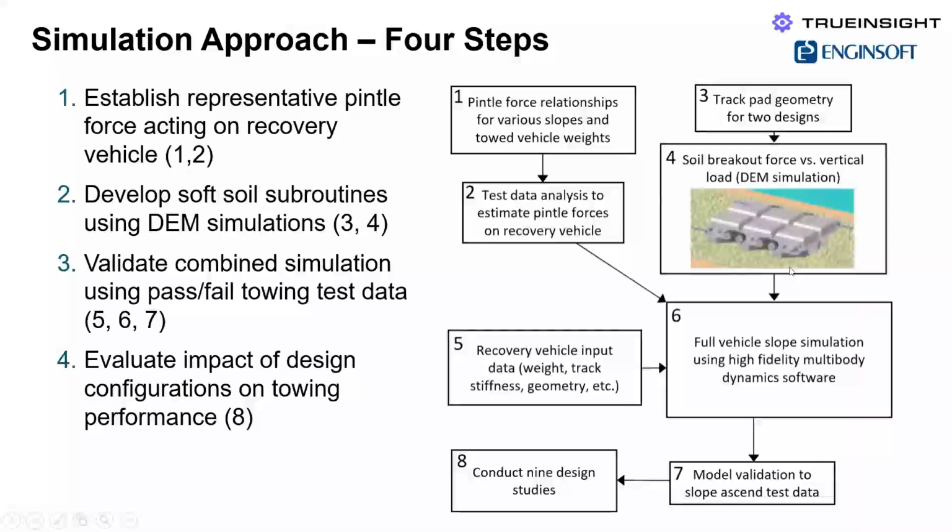Then we changed the distribution of the front to back forces, keeping constant the track tension on these tracked vehicles. So we just changed the distribution of these tensile forces from the rear to the front, and continued to do that until the track links broke free of the soil.